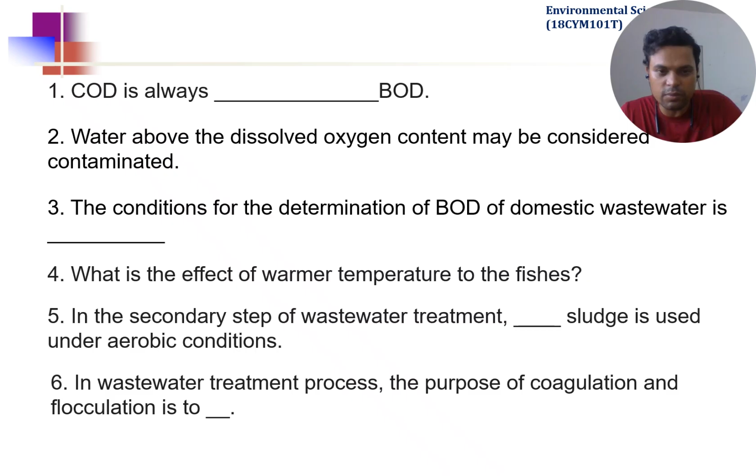The condition for the determination of BOD of domestic water is 5 days incubation at 25 degrees Celsius. I discussed this earlier, so this is actually the same topic, so I just kept all these questions. What is the effect of warmer temperature? What would happen if you increase the temperature? The dissolved oxygen present in water will decrease, so there will not be enough oxygen for their survival, so they will die.